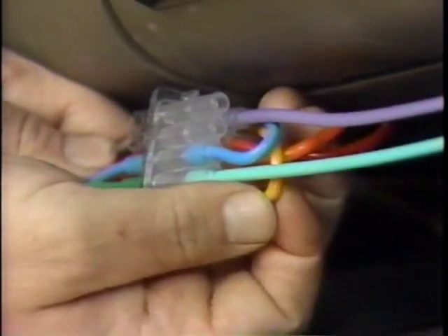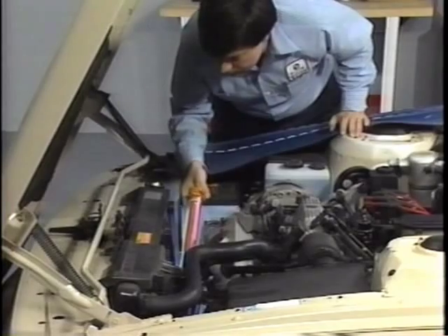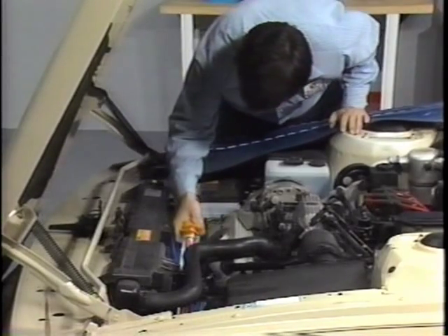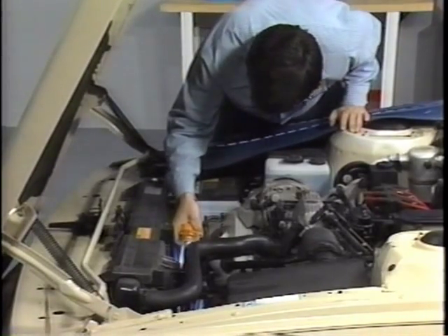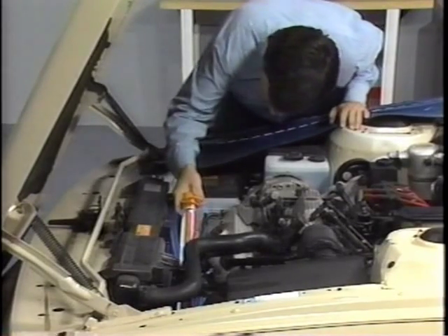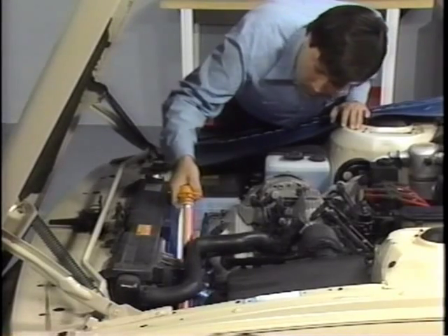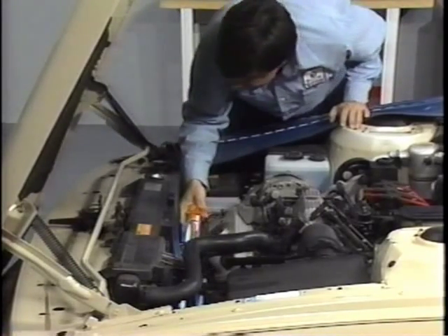It is likely to be caused by a pinched or disconnected vacuum hose. An under-hood visual inspection is another way to quickly pinpoint many causes of air conditioning problems. Begin by checking for leaves or other debris blocking the condenser. Also, check the radiator and condenser for visible signs of damage, and check for blockage in the area between the two. Visually, check for leaks or damage to components.